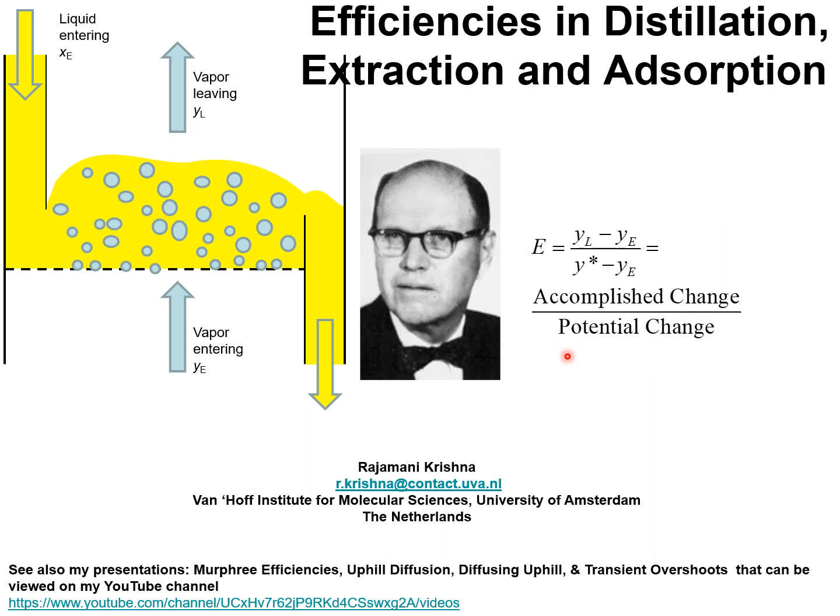Thirdly and finally, I'd like to take a sideways look at transient adsorption of binary mixtures in a zeolite and demonstrate that the component Murphree efficiencies may indeed exceed unity for kinetic separations.